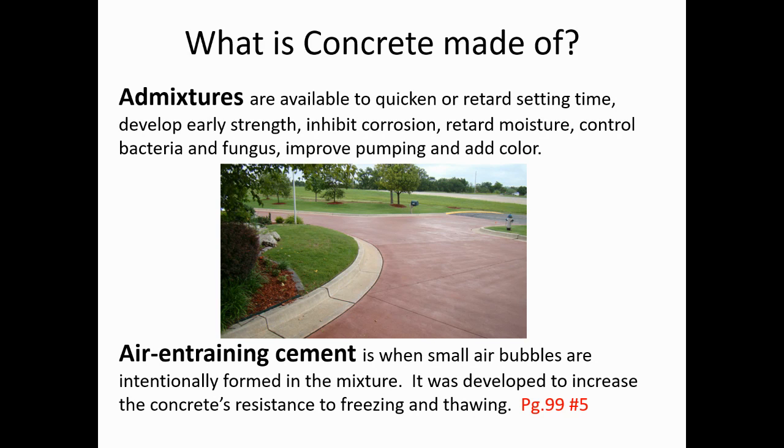All right, and then what happens down the bottom there is something called air entraining cement. What you can do is add an extra ingredient so it creates tiny little air bubbles, tiny pockets in the cement when it's curing. And so hopefully when it freezes and thaws and the concrete expands and contracts, it's got a little more room to expand and contract, and it won't crack.